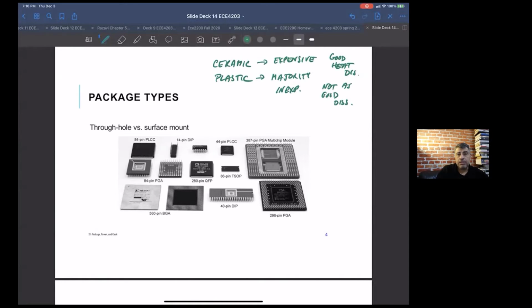The plastic sometimes tends to flake off, and it's not visible, you'd have to look at the part in a microscope. So sometimes, like in our business, because we make image sensors, if stuff's flaking off the package and dropping on the chip, we don't like it. So that's another reason you might not want to use plastic. But the majority of the parts are plastic. Okay, so that's one big fork in the road.